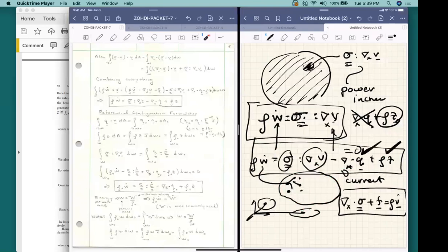No telling what kind of craziness is going to go on there. And then it also has the energy storage. That means that this equation here, the balance of momentum and the so-called power law, they're coupled, strongly coupled. So these things are really coupled together, which means unless you do some simplifications, you can't solve one equation without the other. So you'll see in many doctoral theses, just these two equations pretty much drive an entire thesis, let's say in theoretical mechanics, because it's an extremely rich area of trying to figure out how the stress here interacts with the stored energy and vice versa.